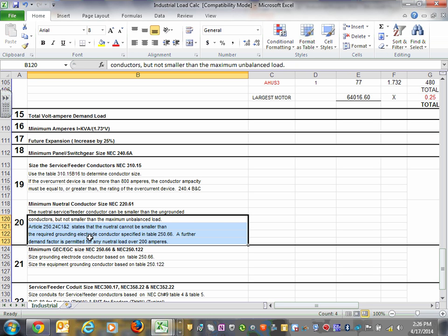Match your panel. If you're trying to cut cost, a good way is to take advantage of the 800 amp. Up to 800 amp, for example, you can have 2 sets for a 400 amp panel. For a 400 amp panel, I can pull either 600 kcmil or I can pull 400 amp kcmil. Both of them are right from a code point of view. From an engineering point of view, you put the 600. Think of voltage drop, guys. There are a lot of issues with voltage drop. So the higher size, in my mind, is always for voltage drop.